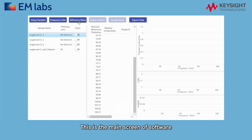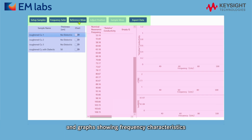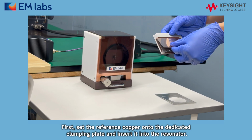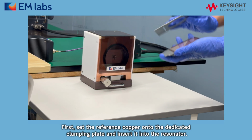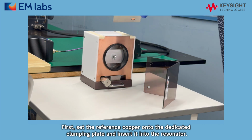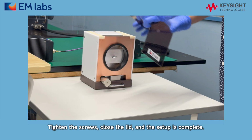This is the main screen of the software. It includes sample information registration, various operation buttons, conductivity measurement results, and a graph that clearly shows the frequency characteristics. Now, let's measure the reference copper. First, set the reference copper onto the dedicated clamping plate and insert it into the resonator. Tighten the screws, close the lid, and the setup is complete.